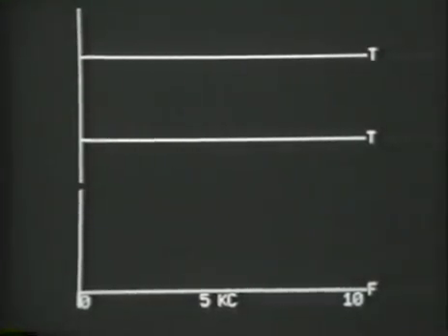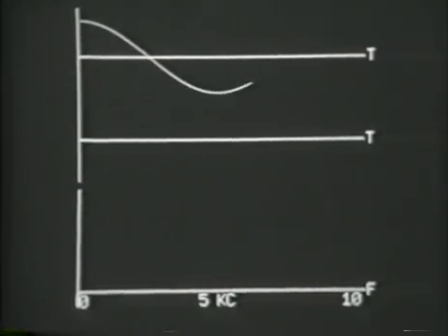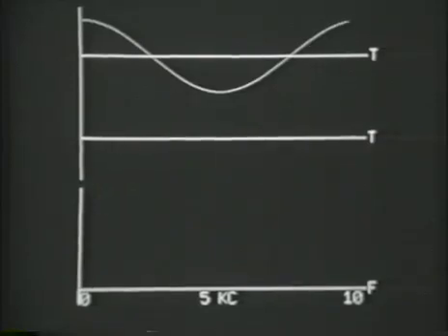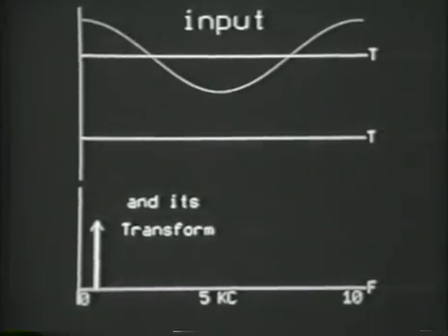So at the top, we'll have the input sinusoid without showing the samples. Its Fourier transform is an impulse in the frequency domain, as we've indicated. And if we sample it, that impulse then gets replicated.